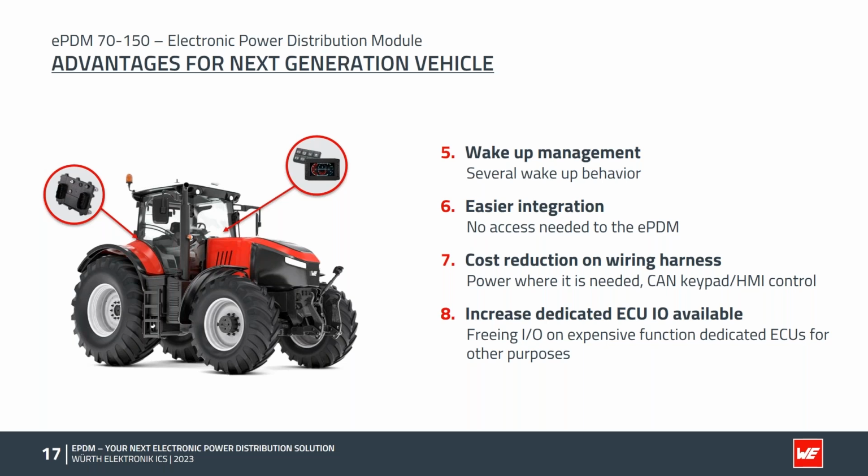The ePDM being placed upstream on the electric system, we can offer an enhanced user experience. For example, we can make several devices, like a door switch on the HMI, straight activated when you open the door without doing anything else, or we can be woken up from the telematic system just requesting a given ECU to be powered on to gather the diagnostic values. Of course, those different scenarios are completely programmable within our programming environment.